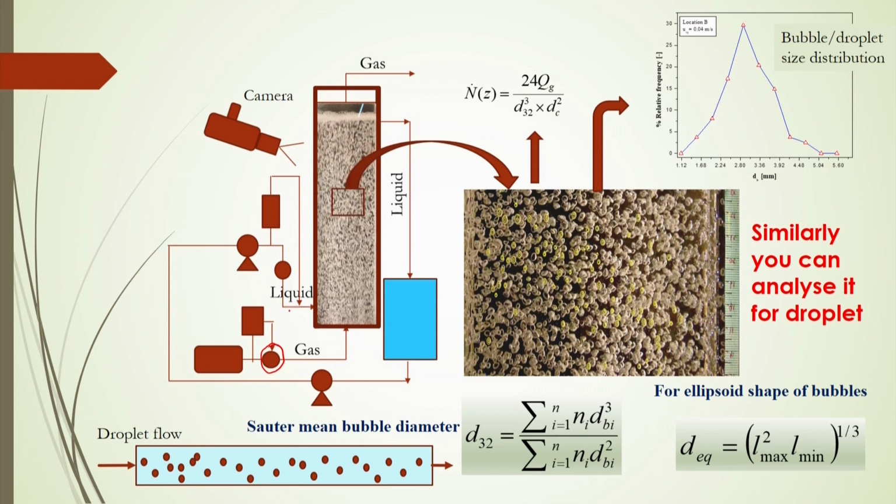And here the liquid is also poured into the column by a pump from a storage tank, and it may be continuous, it may be batch wise. So, if you are considering batch wise, then only some amount of liquid pool will be in the column, and in that liquid pool this gas will be dispersing as a dispersed phase of bubbles.